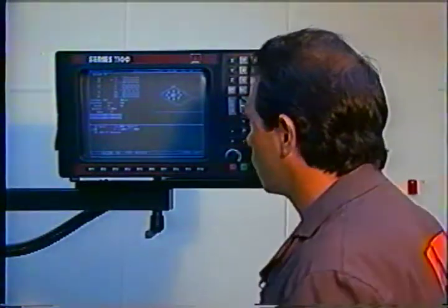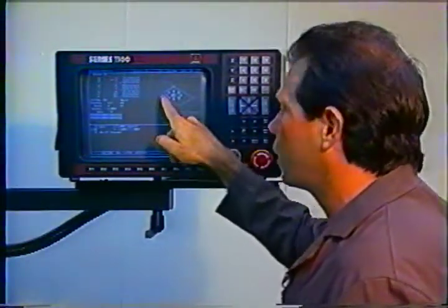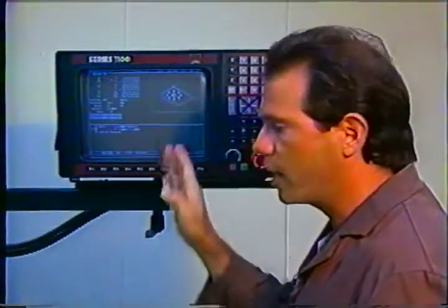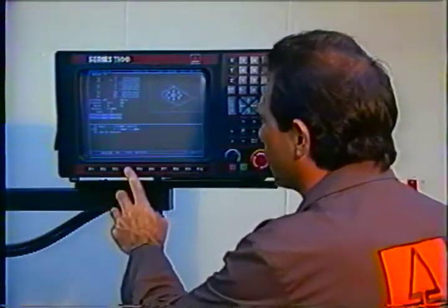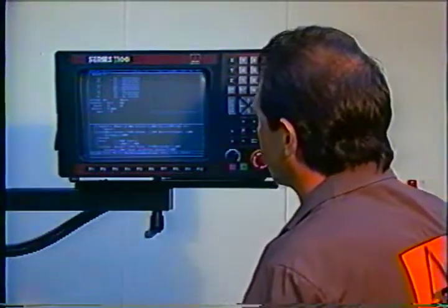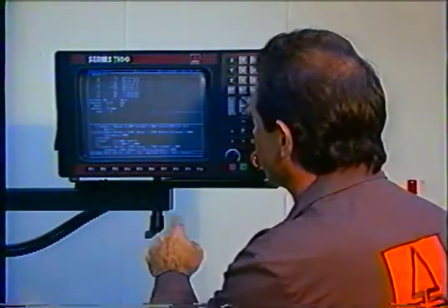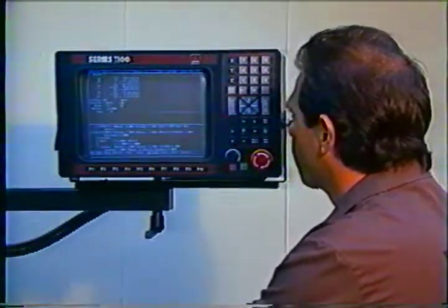Had we not used tool compensation on this corner down here, I would have a complex calculation to figure out where to actually drive my cutter to. So it looked good in the isometric view. We could always take a quick look at it without text or tool in the XY view. I like to look at it in both those views. Possibly even a front view or an end view if you wanted to see some depths on the part.